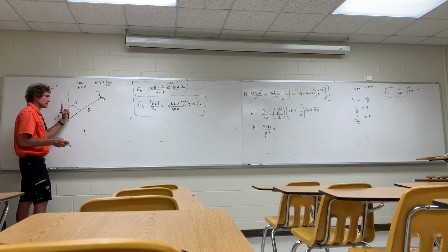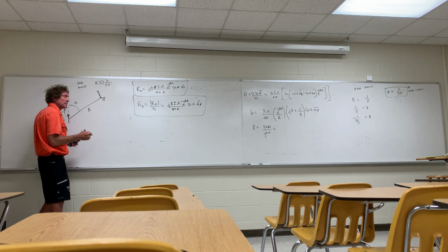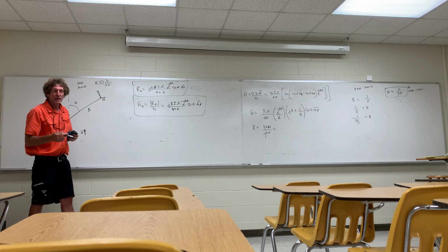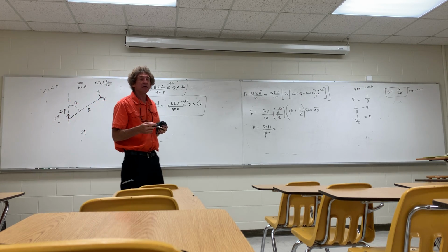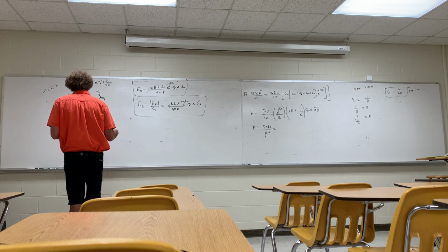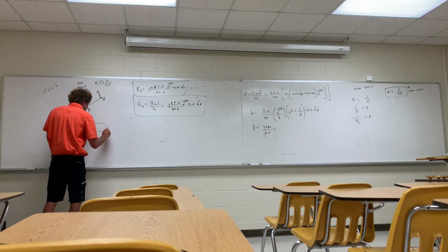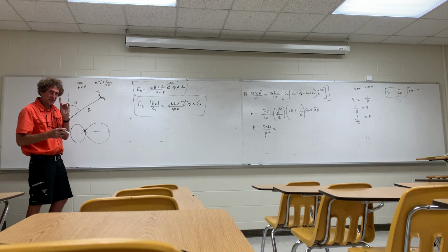The sine of the angle. So directly above, there's nothing. And where does the sine become a maximum? At 90 degrees, right? Sine of 90 degrees is 1. So if you were to plot the magnitude of the E field on a polar plot, it would look something like this. This is where the maximum E field would be. This is the far field.